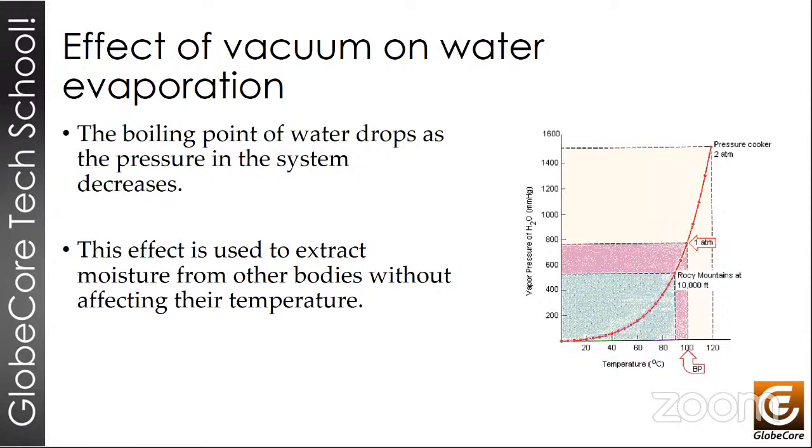We all know that water evaporates at its boiling temperature of 100 degrees Celsius, but that's just half of the story, because if we give the full answer, we should say that water boils at 100 degrees centigrade at 1 atmosphere of pressure. The influence of pressure is very important for the boiling process, because when pressure increases, so does the boiling point, which indicates that they are directly proportional. When the pressure drops, the boiling temperature also decreases.